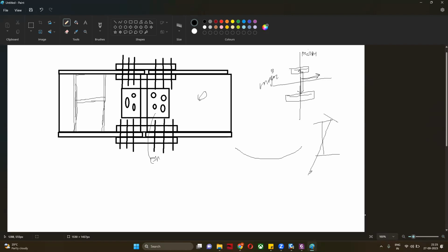All this girder will overall look like buckle, but not buckle, it will be going like globally from one position to another position. It is known as global torsional buckling, or normally people call it global buckling. Sometimes we call it torsion, but it is not just the torsion. The whole girder will try to topple in this direction.